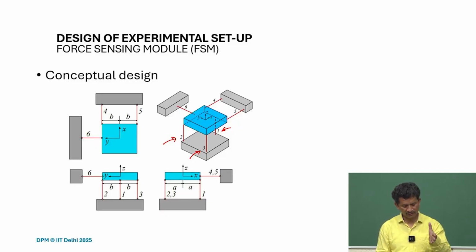So 3 constraints at the bottom support the floating platform. On top of this is how we are going to support the instrument or the entire endoscopic platform, so that when we are operating, the load gets transferred from the floating platform to the fixed frame through these wire flexures.